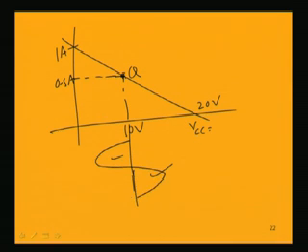This type of signal we are getting, no doubt we are getting a very fine symmetrical swing of the collector current as well as the VCE. But where we are suffering using this type of class A power amplifier is that a huge amount of power is lost. Our efficiency of the power amplifier is very low. In this case, we are getting an efficiency of only 6%. So, a tremendous amount of power is lost, we are getting only a very small portion of what we are feeding, and that is not good.